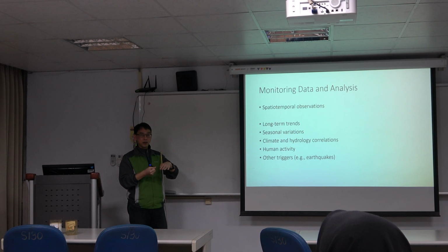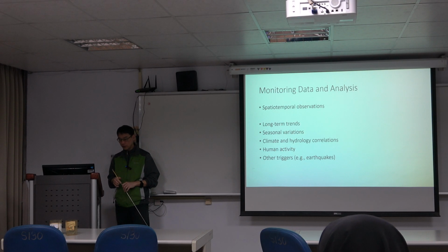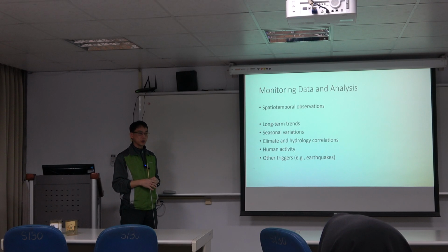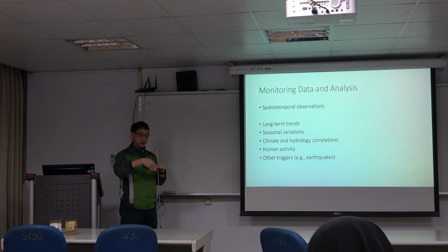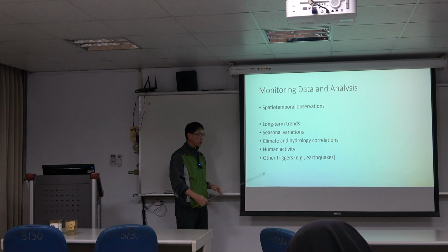And some of the soil, if it is in what we call over-consolidation conditions, will undergo permanent deformation. So you need to be careful not to let the water go lower than the historical levels, because that will induce permanent deformations. If it stays within that, it will behave more elastically and you will not have permanent deformation. Dry season and wet season, they become elastic. They can recover, and they will not induce the problem. So seasonal variation is also a very important part.